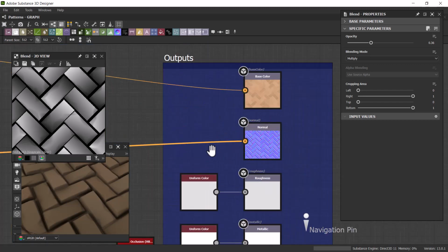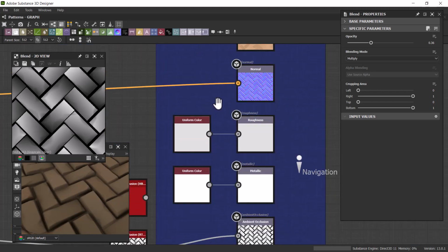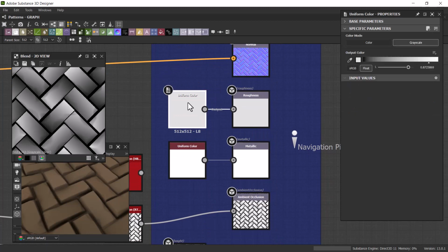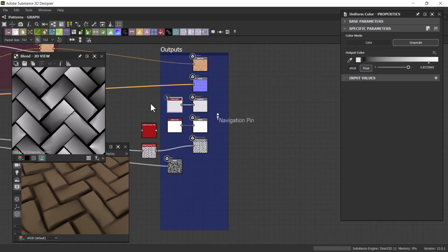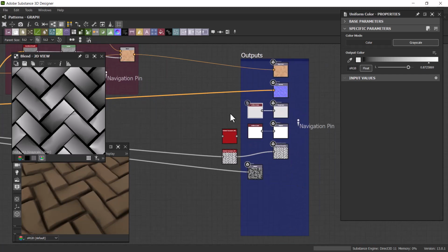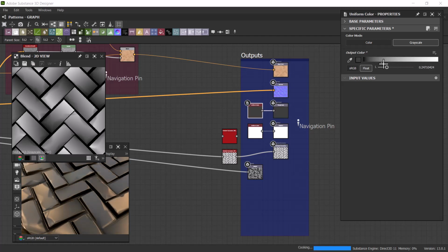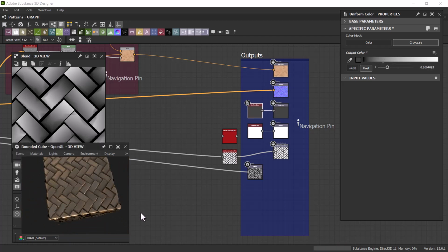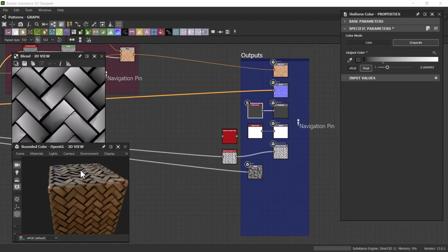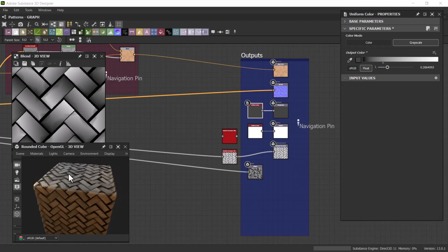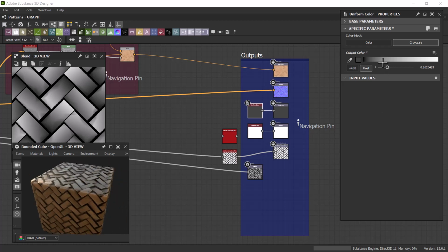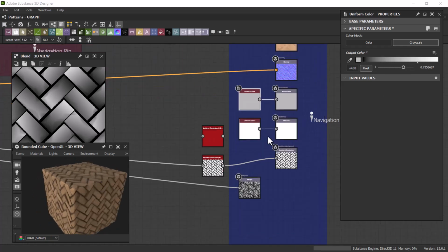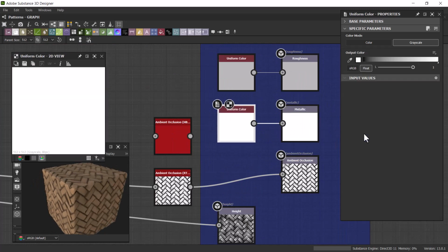So with that information, we can get the base color, the normal, the roughness. Now what I actually like to do is to use this separately, but we can just get that roughness information directly, but I'd like to change the roughness values. For instance, if we make this reflective, we can have something that looks shiny and metallic. That's not the behavior of a brick. That's not how bricks look. They're a bit rough, so it's not going to have more reflection. And we can also change that value for the metallic and drag that midway as well.